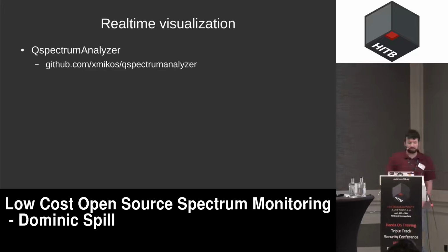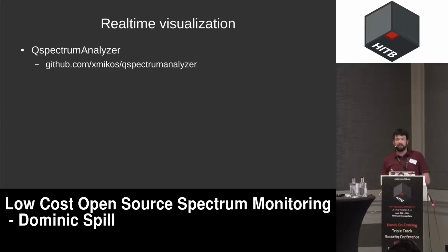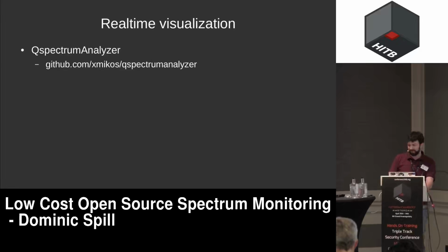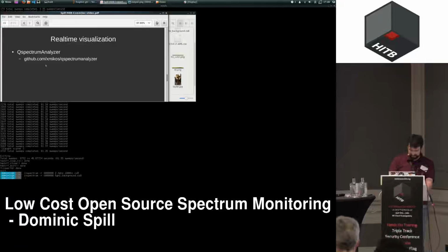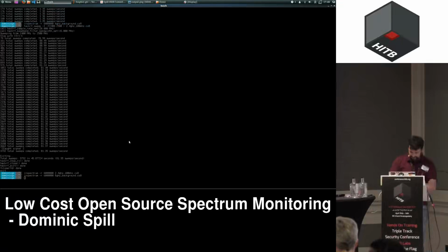But it's potentially more interesting to look at this stuff in real time. I took that sweep over the course of 2 hours. I then spent the rest of the day trying to coax Heatmap into producing an image from it, which I clearly failed to do at reasonable power levels. Turns out it's really important that you remember decibels are often negative, because otherwise, if you think they're positive, everything's out of range. So what I'm going to show you now is Q Spectrum Analyzer,